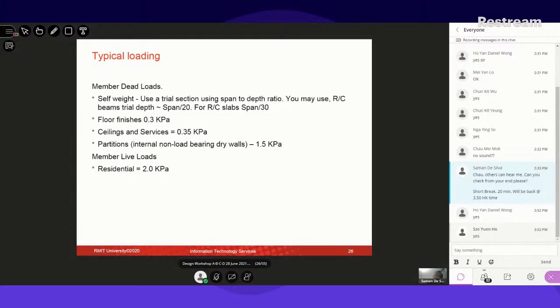is that value. So the recommended value we are using in Australia, I'm pretty sure Hong Kong will have a similar value, but you should say drywall construction will be used with the partitions, and then you will find somewhere around 1.5 kPa is good.